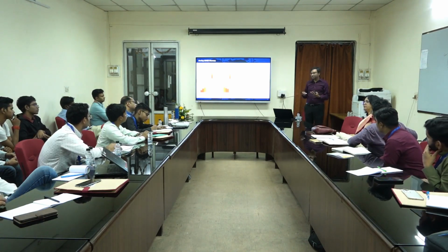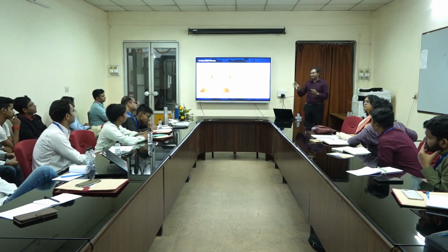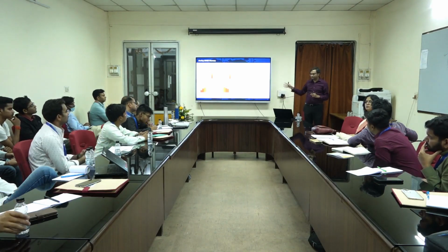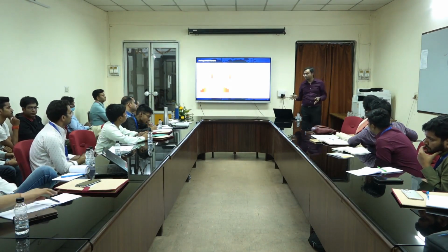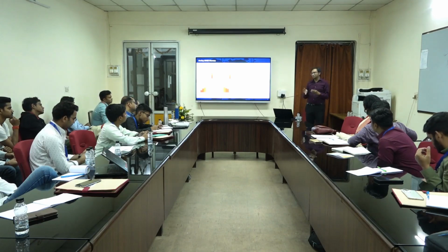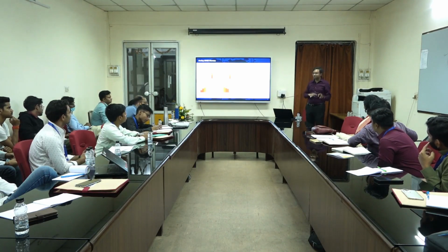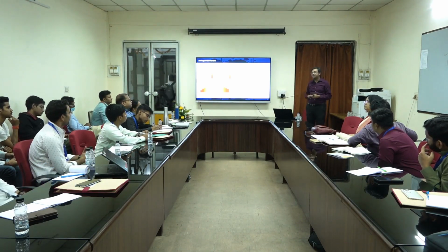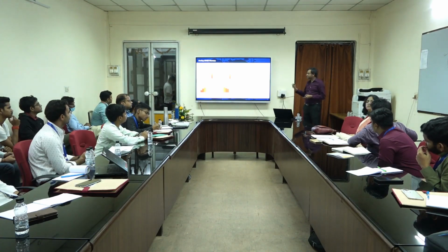Whether it is for training, even in some instances, inference may not require it, you should be able to only read, do not need to write. But generally, ROM is not too heavily used nowadays. You have to use a memory where you can both read and write. That is something that we need for neuromorphic applications. Right? Any other question on the flash?